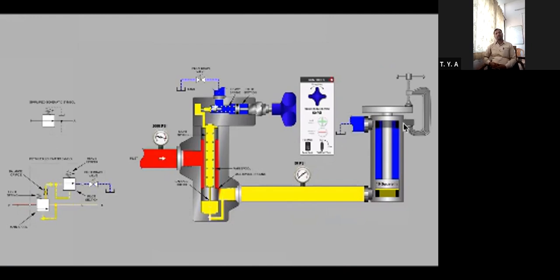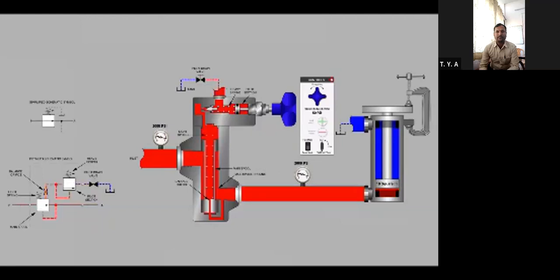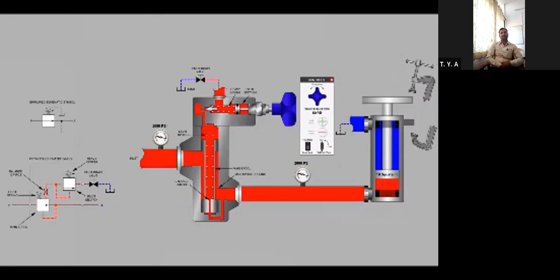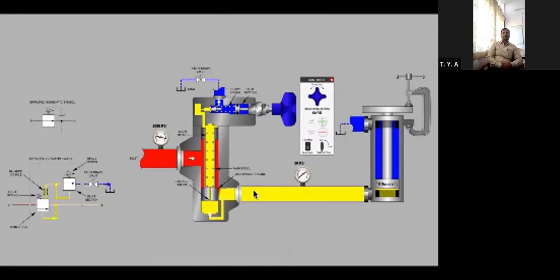While many pressure reducing valves use a normally open or normally passing symbol, once active, the valve has to spend a fair amount of time in the closed position. If the valve was to remain open for any notable period, the full inlet pressure would quickly become present on the outlet line. Remember that there is no continuous flow path in this subcircuit to the cylinder.